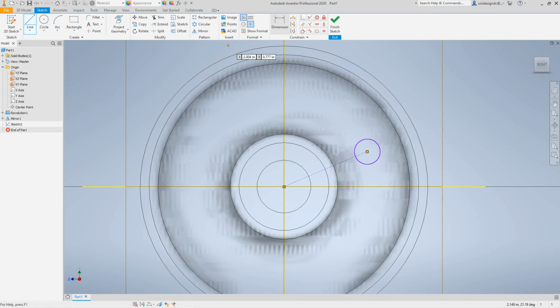And now hopefully this will work. We want to do a dimension from this axis to here. And I want to change this to 30 degrees, and that should rotate if everything's good. Yes, okay. So now that rotates by the origin, which is what we wanted.